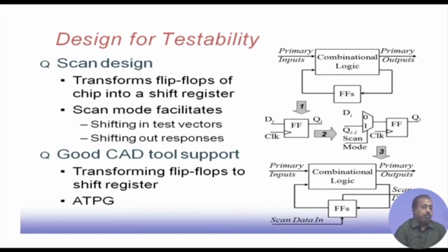The other way out is to have scan design. This is the typical system that we have. Any system will have combinational logic and some flip flops in it. We transform these flip flops so that they form a shift register.